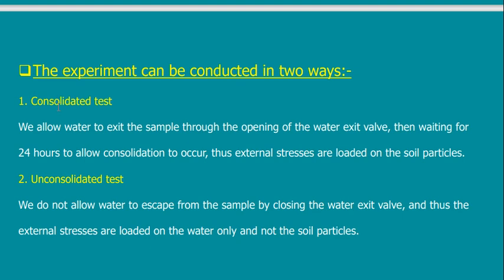So a consolidated test means allowing water to exit the sample through opening the water valve, that's all, or the tap. Then waiting for 24 hours. So I will open it and leave it for 24 hours so that all water can leave this sample. So in this case, it will be a consolidated test.